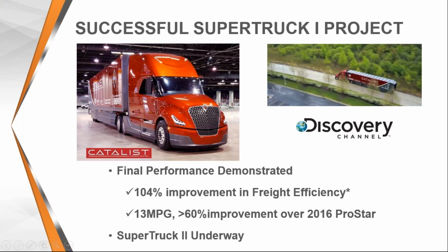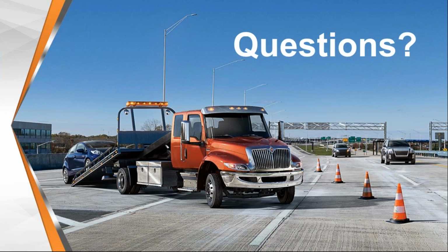Todd asks, are there 2 diagnostic connectors, a black one and a green one, on this particular chassis system? No, I'm sorry if I confused you with that. The black is the older trucks. They will have a black connector. And when we transitioned from the 250K Datalink, they went to the green. The green will let us know that this truck has the 500,000 bit per second powertrain Datalink. So no, only one. Older vehicles will have black, newer ones will have the green.